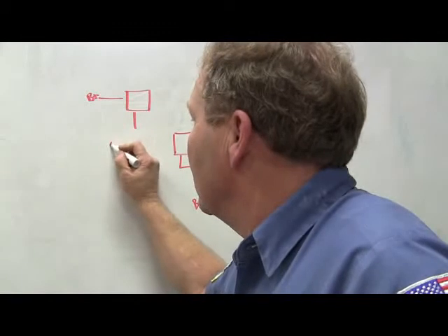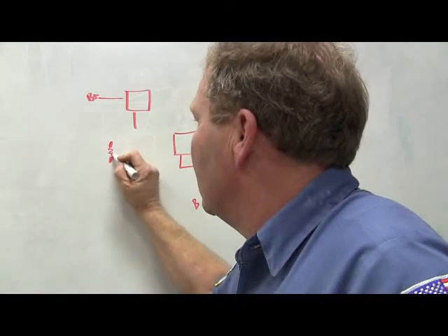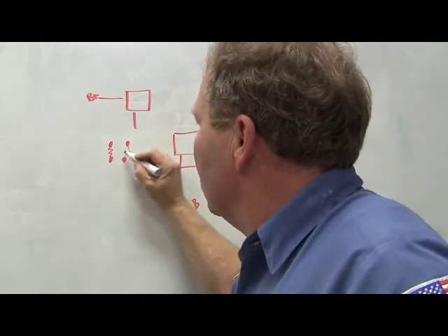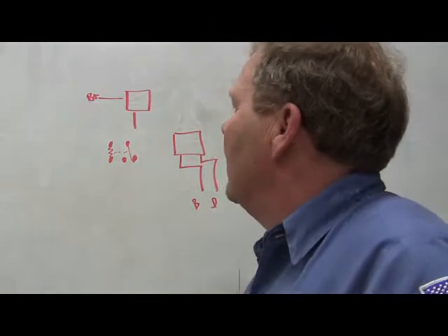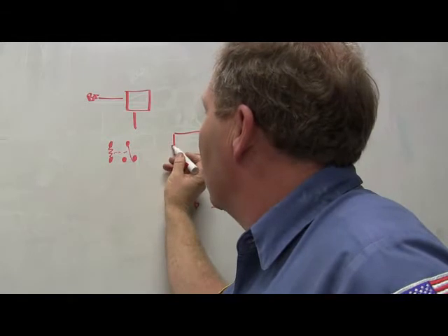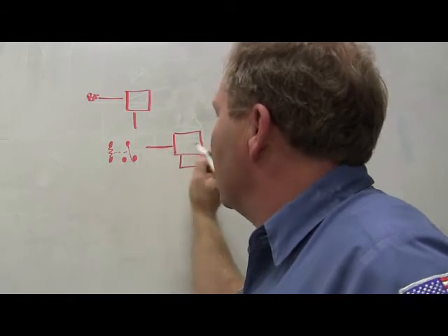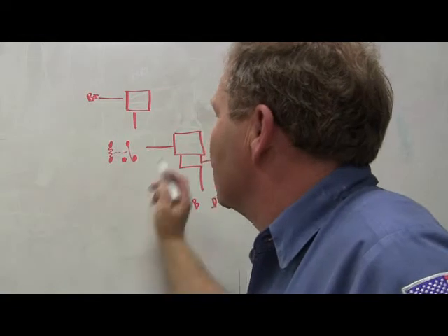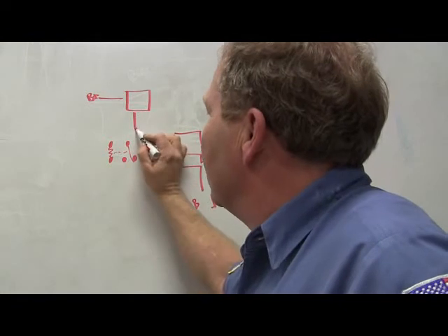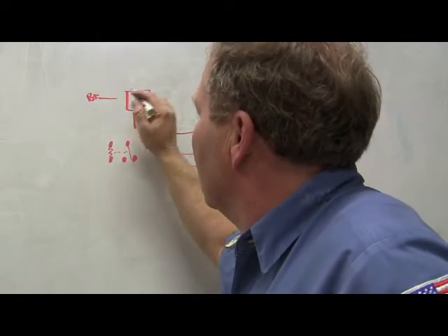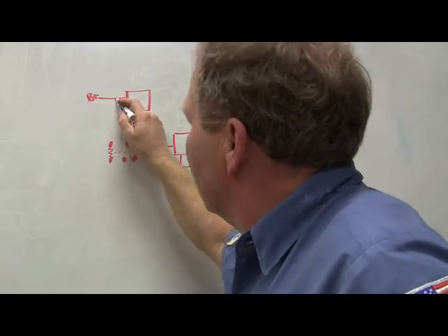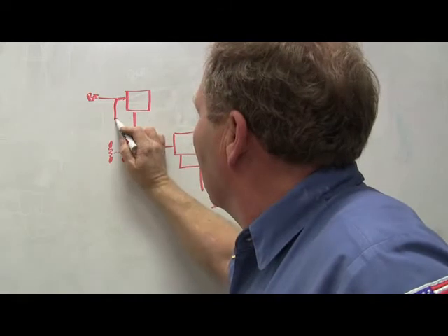Okay, now here's the relay. Let's go ahead and make this a relay. That's the relay, and if you power and ground that relay, this switch is going to jump over. So you've got this wire right here that's feeding your dimmer switch. Your dimmer switch is not the problem, your headlight switch is. The dimmer switch is robust enough to carry it. So basically, I took this right here and cut it loose from here. Actually, I didn't cut it loose from here, excuse me. I came off of it and went right here.